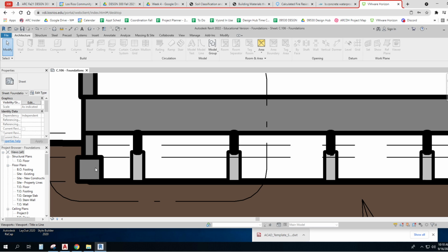Now, concrete is porous, and so water can get into it. And if there are little cracks and the water freezes, that expands and works just like an expansion jack to crack your concrete even more. And then, of course, we know from the failure of the Surfside Tower that water can degrade it and its loads. And if you have rebar, the rebar inside can corrode.